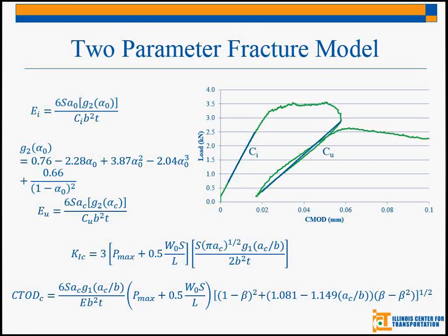What about the fiber reinforced? Was that work also done here? Yeah. What happened there? Lower compressive strength compared to... Yeah, we don't typically expect fibers to increase our compressive strength of concrete or really our tensile strength. They do seem to show a great increase in fracture energy, mainly because they are bridging the gap as you're trying to propagate that crack, and it kind of holds it together. But in terms of compressive strength, it showed a slight decrease here, but typically it really has not a huge effect.